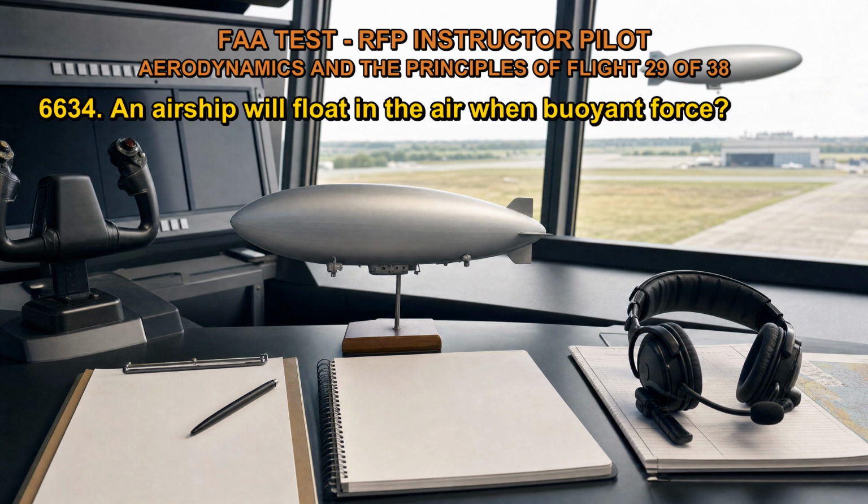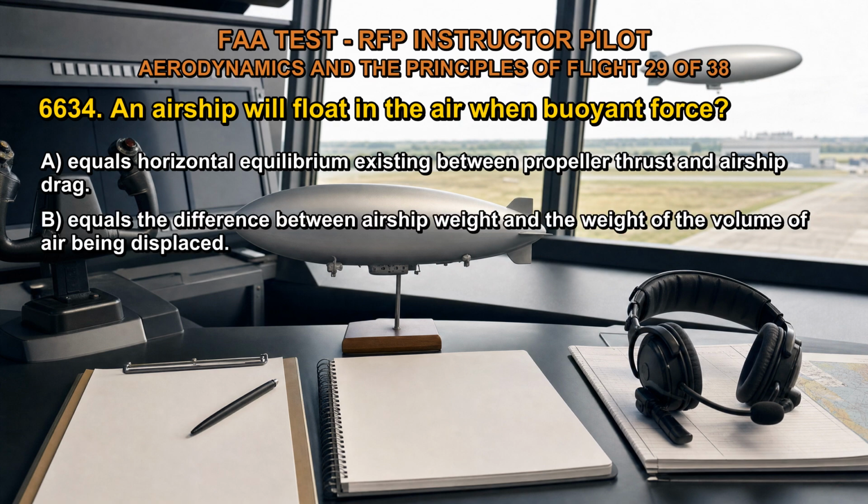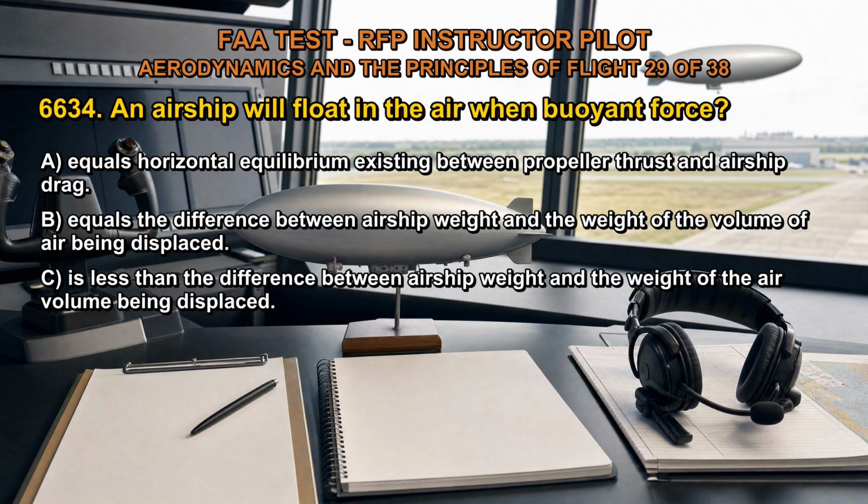6634. An airship will float in the air when buoyant force A equals horizontal equilibrium existing between propeller thrust and airship drag. B equals the difference between airship weight and the weight of the volume of air being displaced. C is less than the difference between airship weight and the weight of the air volume being displaced. The correct answer is B.